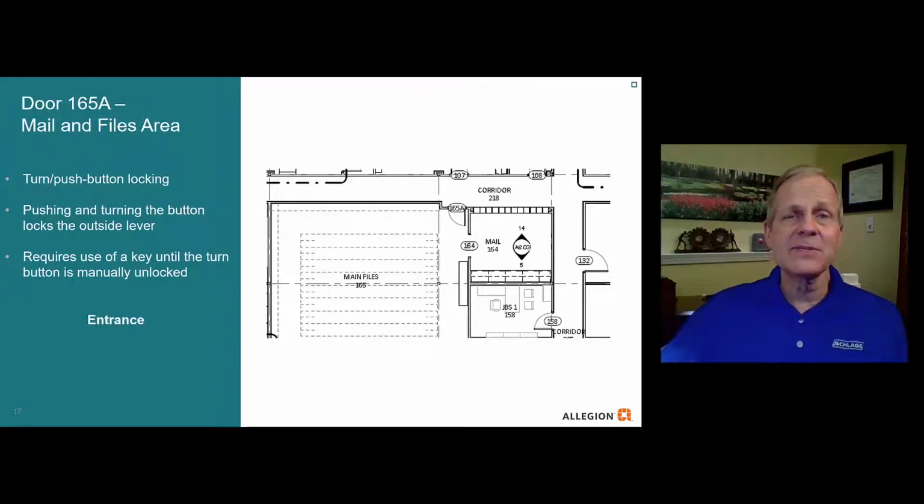So there's a slight difference between entry and office. Generally, the difference is between either a push button or a push turn button. When you have a push button on an office function, when you push down the inside lever, the button pops out. If you have a push turn button on an entry function, if you push the button in and turn it, it's going to stay in, the door is going to stay locked, even when you push down on the inside lever. So just a couple of quite subtle variances between those two different functions.